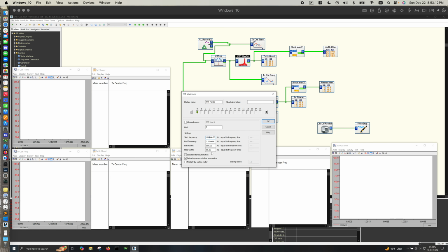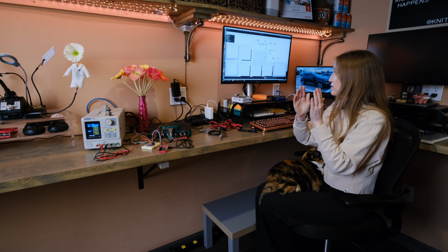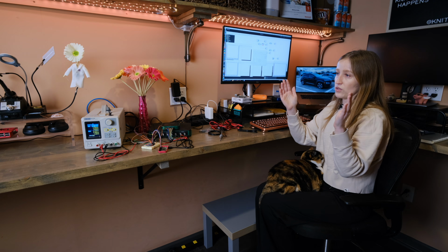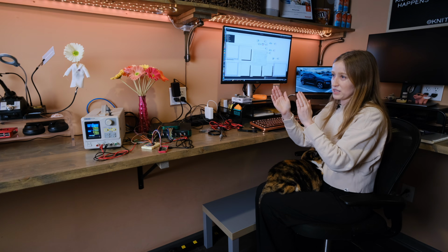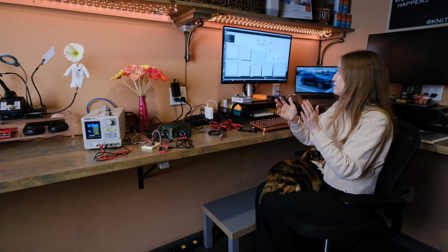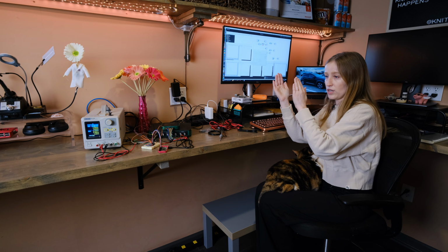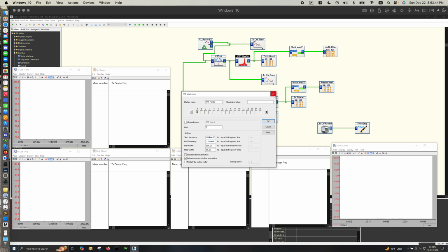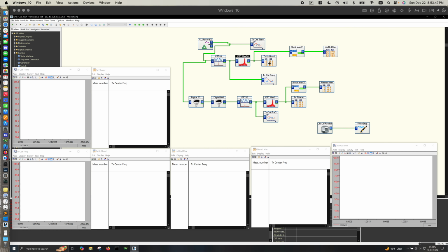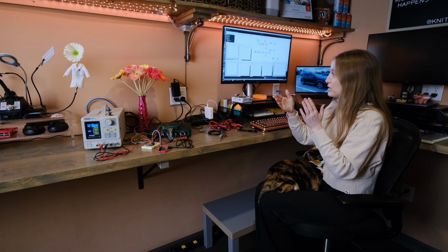And then there's the step width, how big of a step that window takes as it slides across the spectrum. I have that set to 10 hertz. Again, if I had those steps bigger, the sweep would happen faster, and it would take a little bit less computing power because it's not running as long. What the maximum is doing is it has a window that it's sampling as it slides across the entire spectrum coming out of your FFT, and it gives you discrete points of where it finds the highest amplitude in the spectrum.